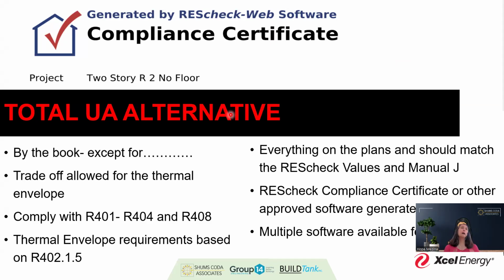You do have some thermal envelope requirements that are going to be based off of section R402.1.5. So that's a section that you're now going to need to really pay attention to. It's not really crazy, but there are some things on there. Now, this is one that I threw in here about the Manual J. When we start talking about all these different components working together, we want to ensure that our values on the plans match what's on ResCheck, but they also should match what's on Manual J. And that's really important, even with choosing the compliance path and understanding the compliance path.